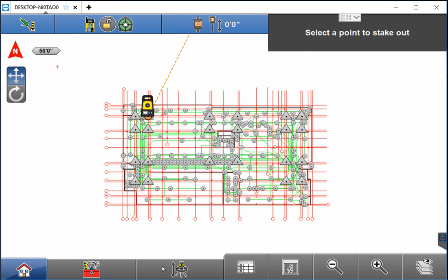Now if you return to the Controller Target drop-down, select Move and Search, and then click Sector Search at the middle top of the circle, the total station will automatically search the predefined area you chose, even if it's pointed in another direction.